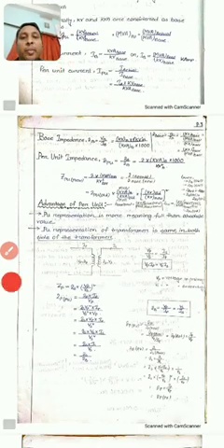go to the base impedance. What is base impedance? Base impedance is V base by I base. Again you can see the V base by I base. So two formulas are given side by side. One is considering kVA as a base, one is considering MVA. So I prefer you go by any one of these methods. If you go by MVA, then this 1000 will not come.